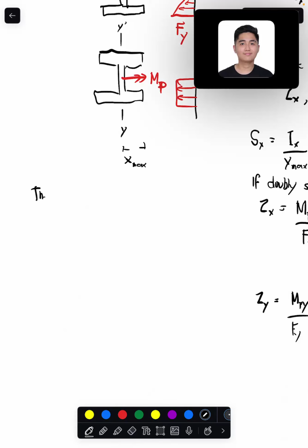If we say the theoretical maximum, what I'm pertaining to is the plastic moment. Or if we say limit state, what's the mode of failure? This is plastic yielding. So, maybe I'll briefly mention that if plastic yielding happens, whether you're in the field or in design, you'll always hear about the formation of what we call plastic hinges.